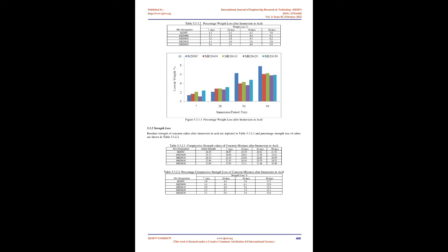Culture of bacteria. The pure culture is maintained constantly on nutrient agar slants. It forms irregular dry white colonies on nutrient agar. Whenever required, a single colony of the culture is inoculated into glass bottles containing nutrient broth of 13 grams in 1000 ml of distilled water, and the growth condition is maintained at 37 degrees Celsius temperature. The medium composition required for growth of culture is peptone, 5 g/lit, NaCl, 5 g/lit, yeast extract, 3 g/lit, urea, 20 g/lit, and calcium chloride 5 grams/lit. 4.0 Experimental Program.